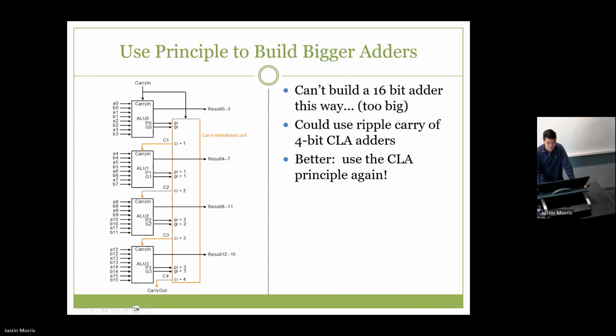And then what is this going to be? The 7th bit, right? And then the 13th bit, as well as the carry out. So these are carry look aheads, and they're connected to another larger carry look ahead. And you could also just connect these all in ripple carry, right? If space was a concern for you and performance was not, the ripple carry might be the better option.